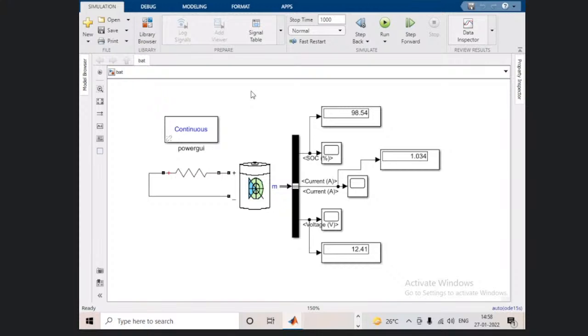This 0 will show that the battery is 100% charged. You need not do further charging, or this diode will control the further charging. And if it is 1, there is a need of charging. So this diode we are implementing here to control the charging and the overcharging effect on the battery pack. Now we will see this battery connection.